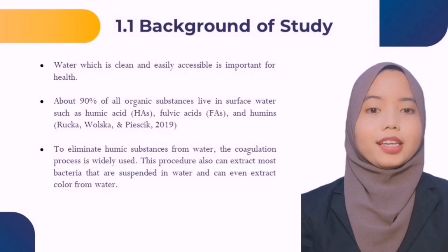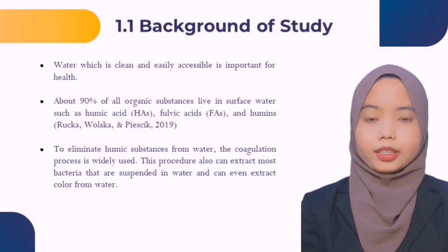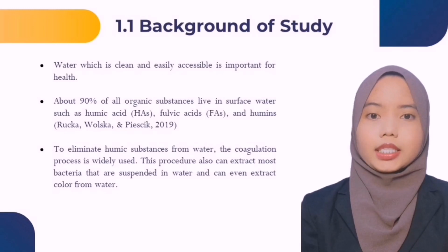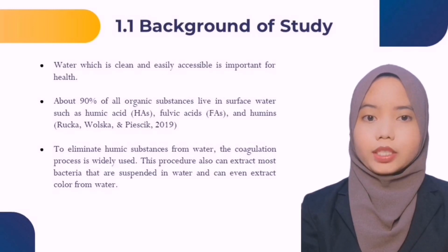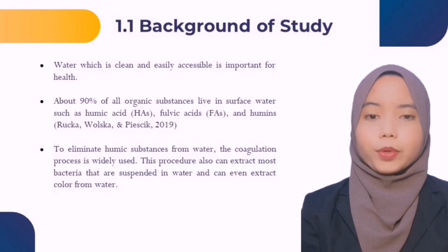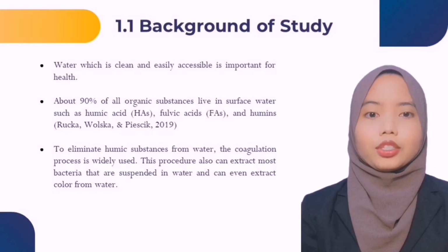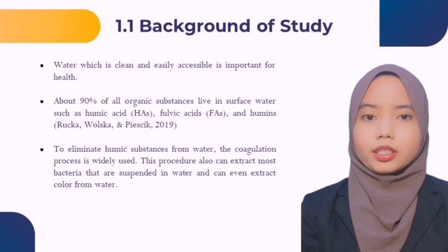Water is necessary for living things to evolve on the earth. Water which is clean and easily accessible is important for health. About 90% of all organic substances live in surface water, such as humic acid, fulvic acid, and humins. Rukha, Woska, and Pisit stated that it cannot be consumed without pretreatment since it can cause water disinfection by-products such as trichloromethane and chloroacetic acid, causing a direct health risk of exposure from consuming polluted water.